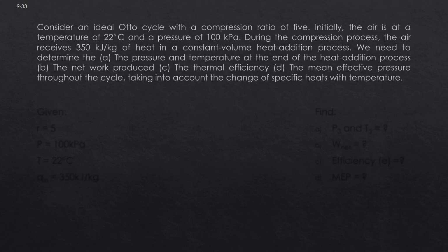Listing all the givens, we have r, the compression ratio, equals 5. The pressure is 100 kilopascals. The temperature is 22 degrees Celsius. And the Qin, or the energy input, is 350 kilojoules per kilogram.